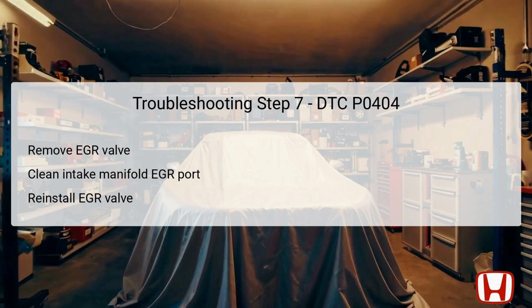This step is vital because even after confirming the internal circuitry and connections are intact, carbon buildup can often cause reliability issues, making regular maintenance crucial. Completing the troubleshooting process involves substituting a known good EGR valve, which effectively serves to validate the original valve's functionality.